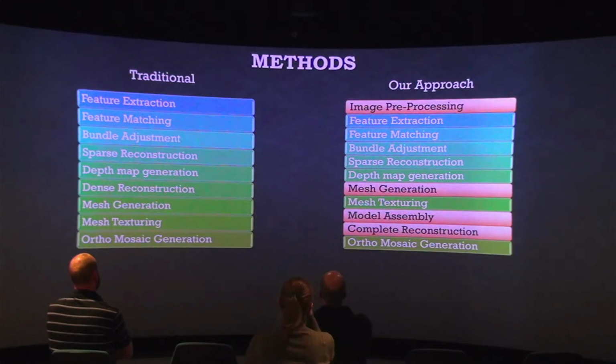For this reason, a number of additional distinct processing steps and a modification to the workflow was necessary. These additional steps consist of data pre-processing, reconstruction of the bow and stern sections separately, which would involve a full mesh reconstruction and texturing from the depth maps, meshing from the depth maps rather than a noisy dense point cloud.